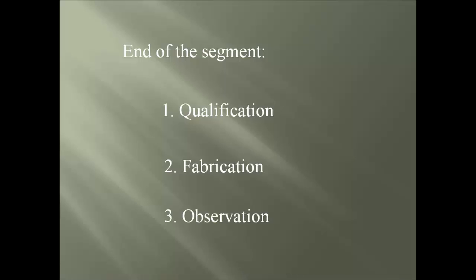And lastly, number 3 was the observation of the welding for sheet steel, which brought to our attention the proper preparation, like smooth surfaces, then the proper fit-up of the base metal, while closing with proper welding, like the current being in compliance with the approved WPS at all times during the production.